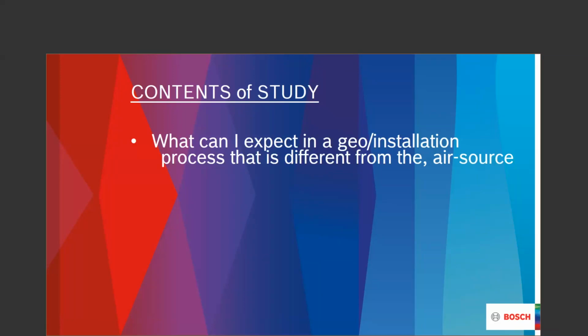The water to water is a very great piece of equipment. It allows us to heat a structure, heat the floor, heat the walls, heat the towel rack, whatever we may want to do with that particular water to water system, and even in some cases cool the space through some air type situations in coils. But we're looking at a very efficient way to heat the mass and then not heat the air. So a water-to-water type system is a very good way to